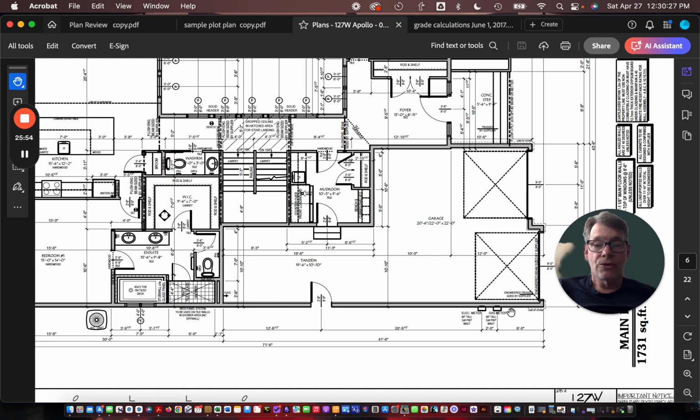So they're drawn there. Now, the reason why we want to have this on the drawings is so that the builders know and can set things up. So, for example, in this case, we would probably have a bit of blocking so that those meters can be hung well from the blocking that's been provided. So easy for the framer to do that during framing. Horribly awkward to do it afterwards, belatedly. So we try and get these things done early on.